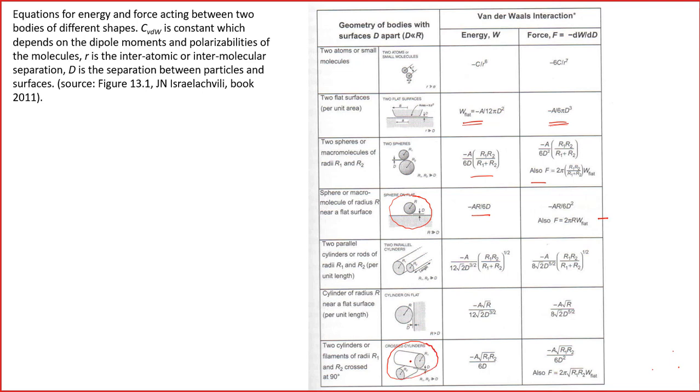So this is also a very useful geometry because there is a surface force apparatus which is based on this one. In this case, we can use these equations and we can find out Hamaker constant or surface energy of different solids, interfacial surface forces. So these kinds of experiments are done which can be related to adhesion and friction and wear.